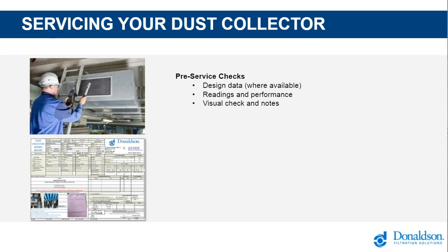So where do we start with servicing? One of the key things is knowing what you're actually starting with. It's really important we document how the collector and the system is performing prior to the service being started. So take performance readings, and compare these also at the end of the service. It's also worthwhile taking notes and photographic evidence as you go along. They all form part of really good service historical data.